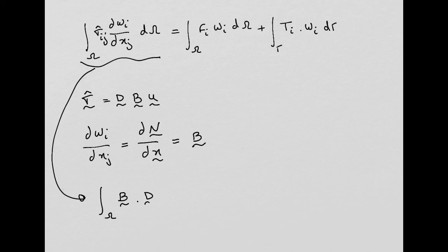So we have the matrix with the elastic constants multiplied by the strain displacement matrix and multiplied by the vector u with the degrees of freedom or with the unknowns. But this is constant, they are constants, right? They are the degrees of freedom at the nodes of the element. So they are constant. I can send them outside of the integral.